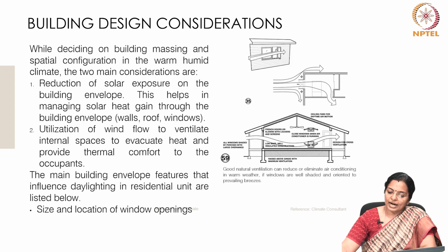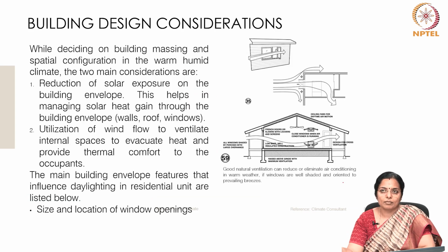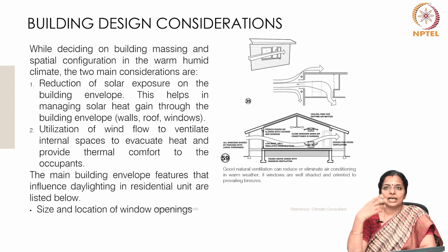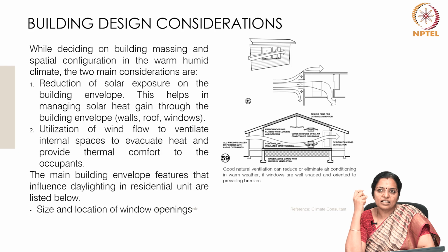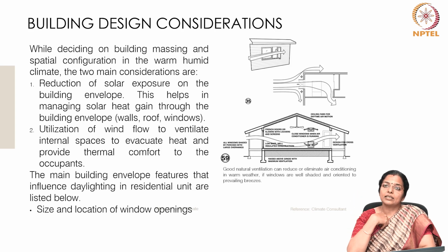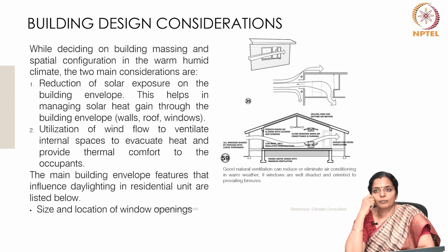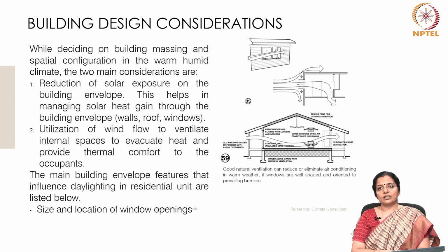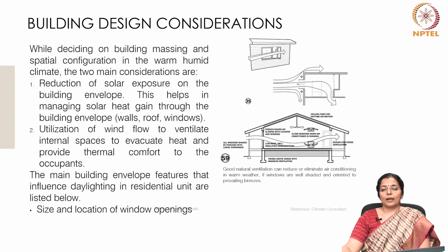So let us look at the design considerations in detail. Warm and humid climates are characterized by high temperature and high levels of humidity throughout the year. This climate type, which is found in the tropics, is also a place which has more population. Hence, it's important for us to understand how to design in this climate type, as it will benefit a large number of people. Frequent rainfall is also a common characteristic of this climate, and in some locations it rains almost every day. These conditions also create a good ambience for insects and moss to grow.